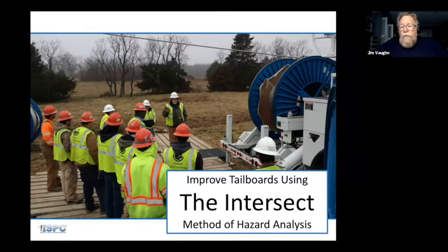One of the things they do when you terminate an underground cable is put the concentrics all together and bond them to the ring bus on the inside of the cubicle. When they were flipping that piece of copper around, they got it into the top of that little transformer. 4 kV creates a pretty big blast of heat and air, and it blew up and knocked him back.